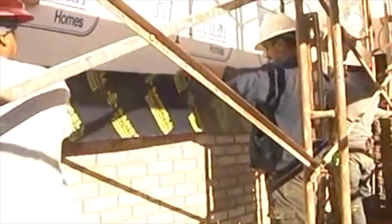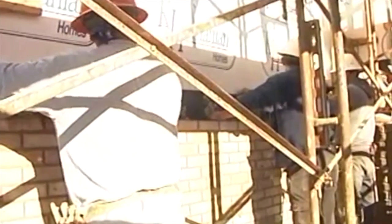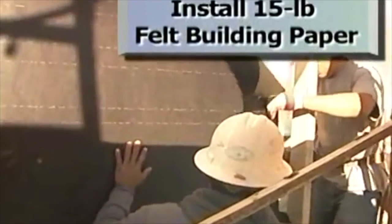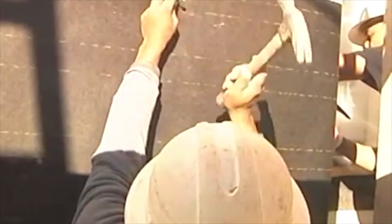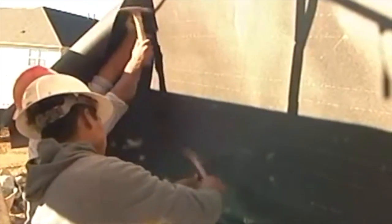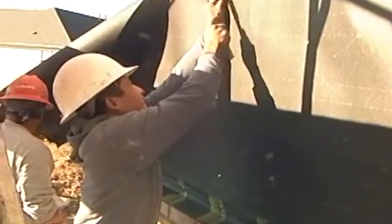There are many flashing products to choose from; this building uses a flexible flashing material. 15-pound felt building paper is installed over the flashing and house wrap, providing a second weather-resisting barrier, although 2 WRB layers are not required by the local building code.